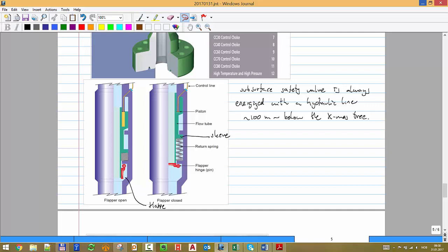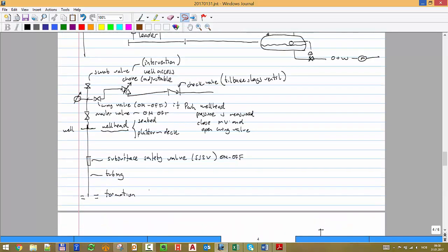In all of these cavities you can have the growth of scale, erosion, and sand accumulation, and then it might happen that if the valve closes, it doesn't want to open later, or if it's open, it doesn't want to close. So this equipment causes a lot of issues in operation, but it is necessary for safety, and you have to make sure it's operating properly all the time. It has a lot of issues, especially with scale and sand. It's locked either in the open or closed position.